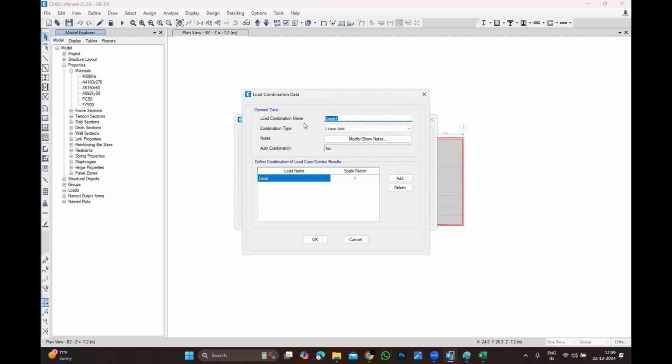So for the stiffness, can I increase the number of columns? That is not going to be possible, right? Can you add the beams? No, it is not possible because people are going for a flat slab. The only possibility is where the core wall and staircase are, by increasing thickness by 25 millimeters, 50 millimeters, 75. These are all to increase your mass stiffness from down to top. Huge stiffness, from base till top.